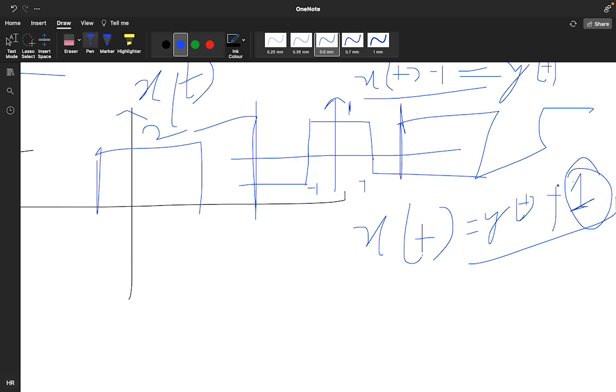So this y of t will only contain even terms, meaning cos functions, and because it is half wave symmetric, we get odd terms only, like a1 cos omega naught t plus a3 cos 3 omega naught t, and so on, plus some DC value, that is 1, because we shifted this hidden symmetry in this form.